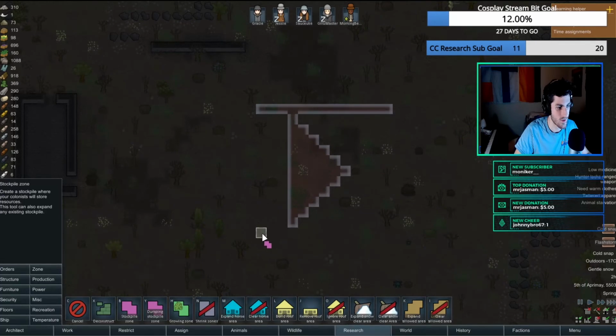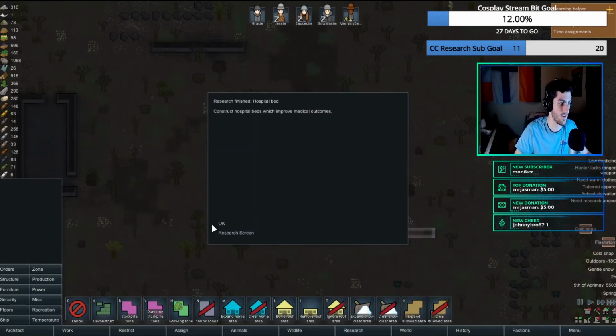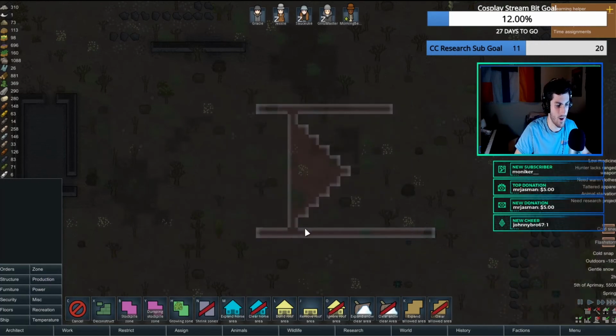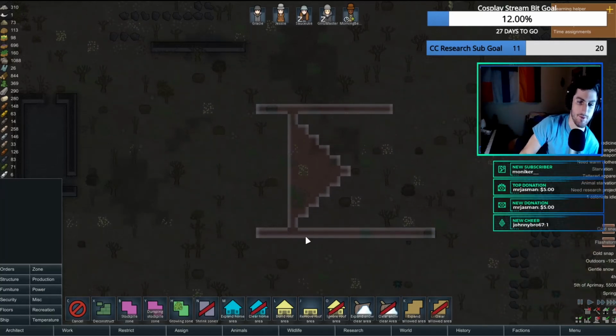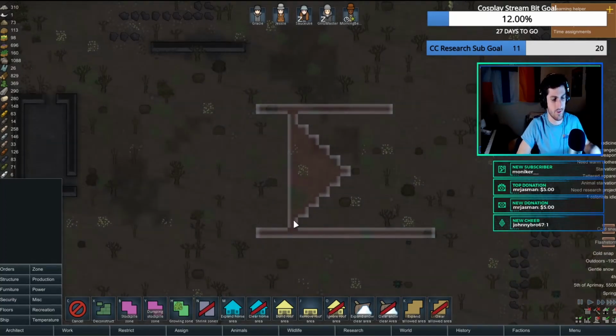So there's this thing called a no-slip condition. Basically, if you have a particle that's on the wall, it has to have the same velocity as the wall. That's how it works. So because of the no-slip condition, if the wall isn't moving, then the fluid at the wall isn't moving.